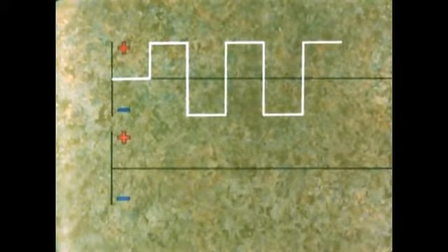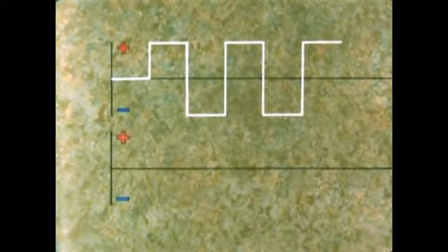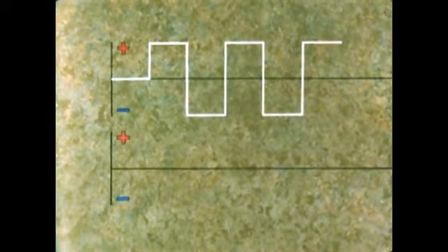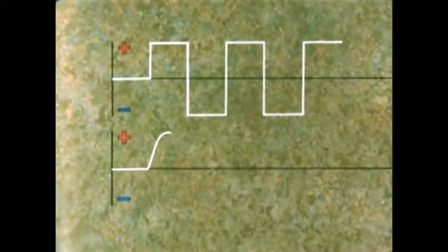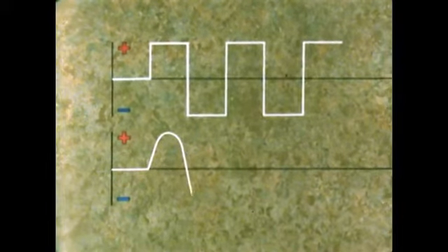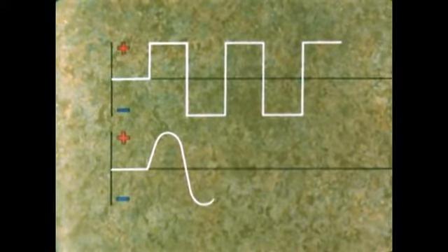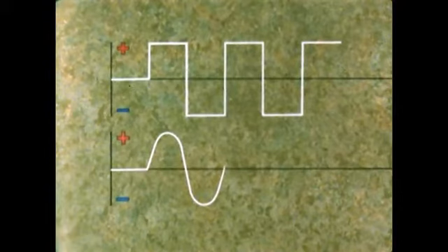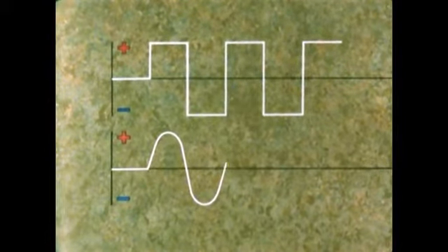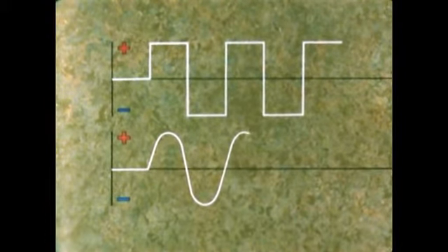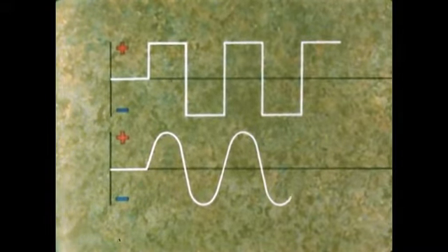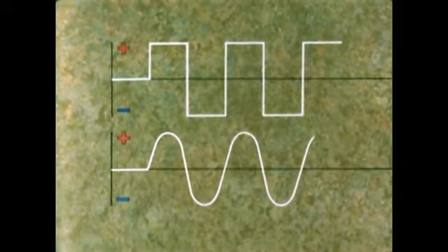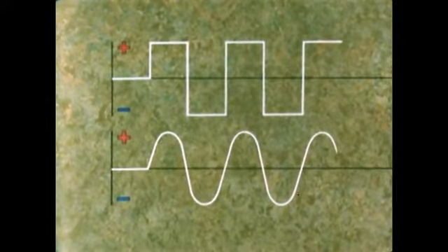Now in most circuits, in practice, it isn't a sudden instantaneous switch of direction like this. Usually the current builds up one way and then decays down through zero to build up again in the opposite direction, before decaying back again to zero. Gradual build up one way, decay. Build up the other way, decay again, and so on. This produces the sine wave.